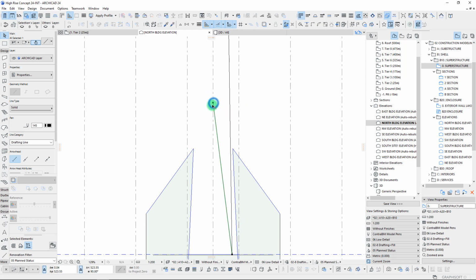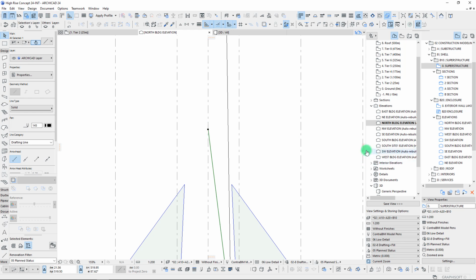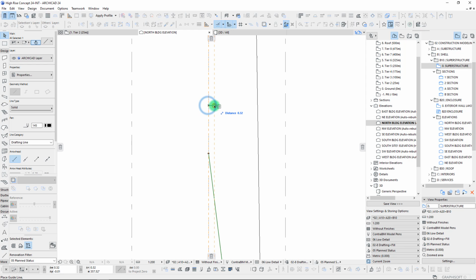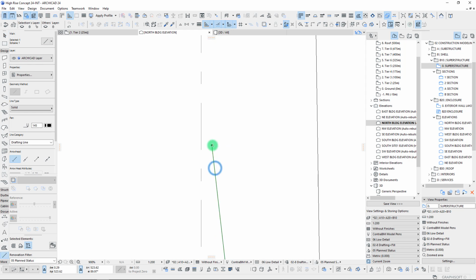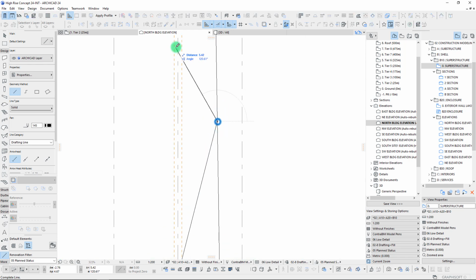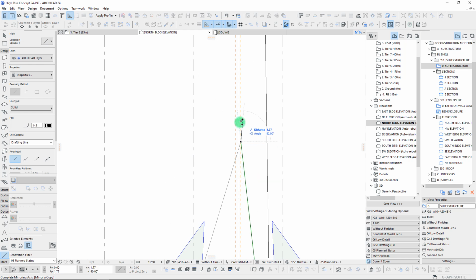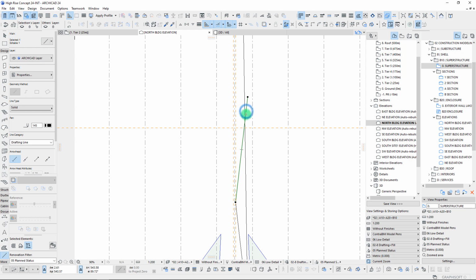So what I'm going to do is start with some basic points, some triangles, and I think I want to throw out a few little guidelines here, and let's offset this from the center, maybe 0.25 meters. We'll go back in the other direction, 0.5, and so now we have some little reference planes to play with. So let's just keep going up. I think I want to make those triangles essentially mirror, well, now that I'm thinking about this, what happens when we take the same angle of this one, mirror it up, and then just trim it at each step? How is this going to play out?